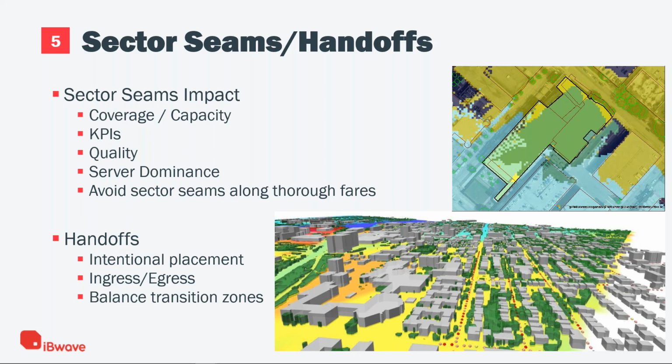They're just waiting on you to provide coverage, which also will impact your capacity plan for the number of nodes that you're using. You may realize that you need to sectorize those nodes and use panels instead of an omni configuration for that node. And so a cantenna may not be your best option. You may need to put panels facing opposite directions and create seams or sectors in your plan.